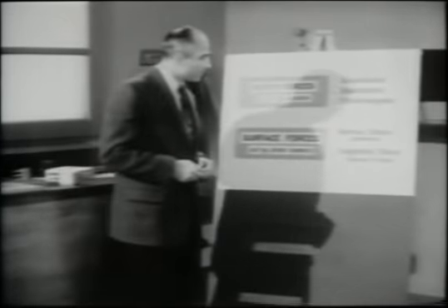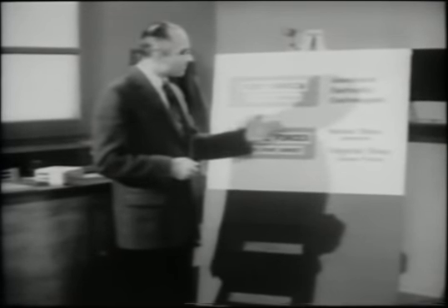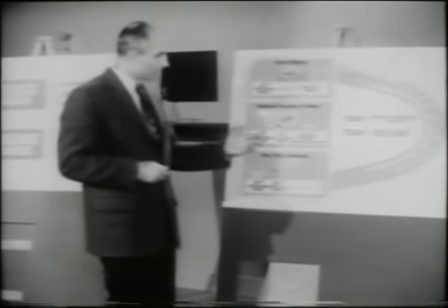We resolved the surface forces into two components: pressure forces acting normal to the surface and viscous forces acting tangentially to the surface. We saw that these forces control the motion of a fluid particle through Newton's law, which relates the net pressure force on the particle and the net viscous force to the inertial resistance to acceleration.